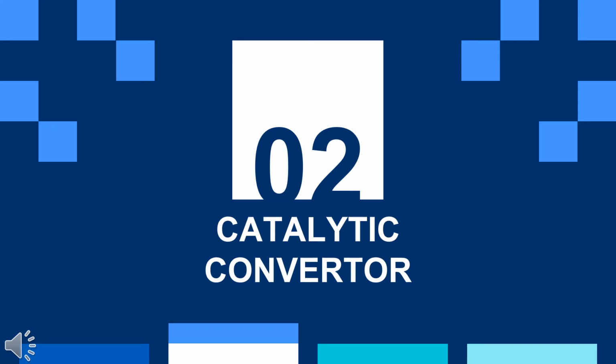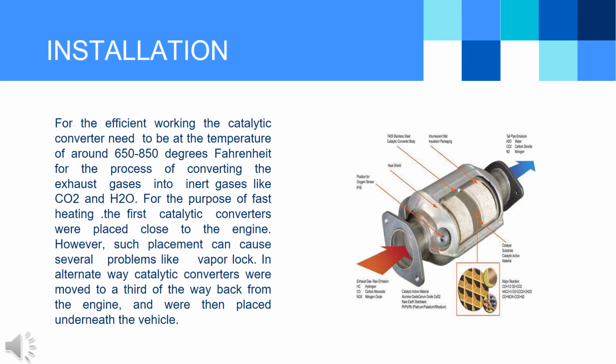The performance and the design of the catalytic converter has arisen from the improvement to vehicle and pollution control code. Now we can see about the catalytic converter. The first and prior step is the installation process of the catalytic converter. For efficient working, the catalytic converter needs to be at a temperature of around 650 to 850 degrees Celsius to produce the inert gases like CO2 and H2O from the exhaust gases. For fast heating, the first catalytic converters were kept close to the engine. This placement can cause several problems like vapor lock. In the alternate way, catalytic converters were moved to a third of the way back from the engine and were then placed underneath the vehicle.